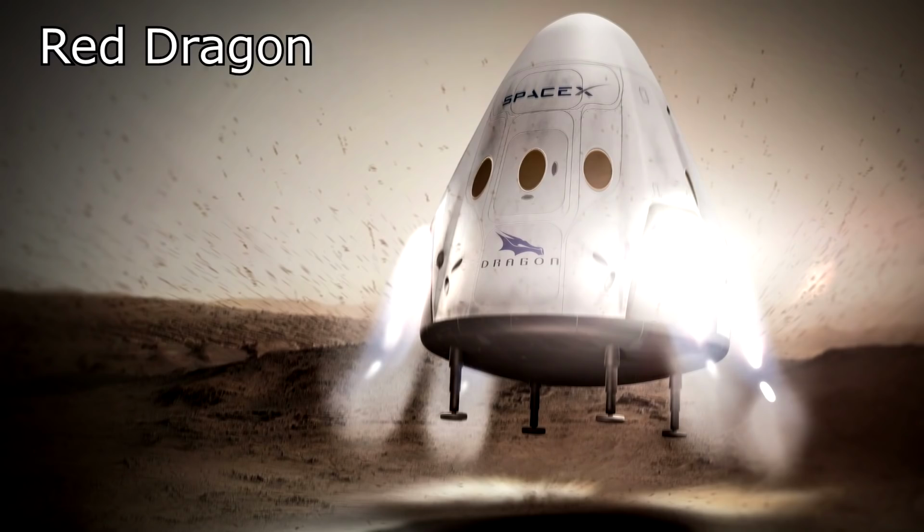Well, the answer is easy. The Falcon Heavy is quite capable of putting a Dragon capsule onto an escape trajectory that will go to Mars. That's totally possible. And we know this because SpaceX were actually proposing something called Red Dragon, which would be a Dragon capsule that would actually land on Mars using hypersonic retropropulsion. It would use its aerodynamics to steer its way through the atmosphere and keep itself up until it slowed close to supersonic speeds, and then it would use the Super Draco thrusters to land. SpaceX was seriously proposing this and hoping that NASA would fund it. It never happened, but yeah, we do know that a Falcon Heavy is totally capable of putting a Dragon capsule with crew up to the velocities needed to rendezvous with the cycler. Now, of course, the problem with that is you have to be 100% sure that's going to work, because there's no abort options or anything for this.